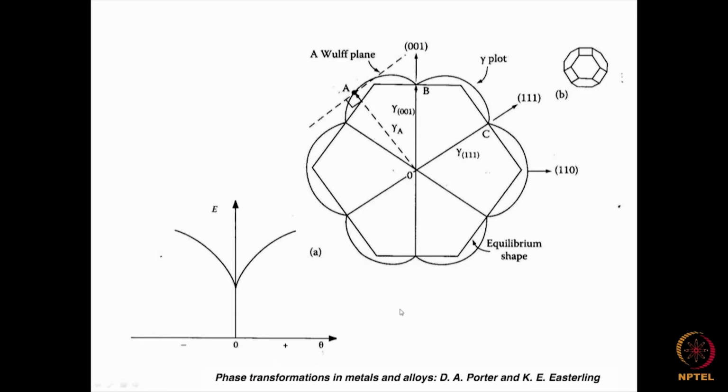That means that if we know the surface energies, or the minima in surface energy occurring at different planes, the morphology which the crystal can have is going to change. That will be determined by the relative energy difference between the surfaces. Here this is a specific case for an FCC which is being considered. For all the samples, we are going to get a surface of similar type only. This is going to give the equilibrium shape. If a void forms, it should have this type of shape.